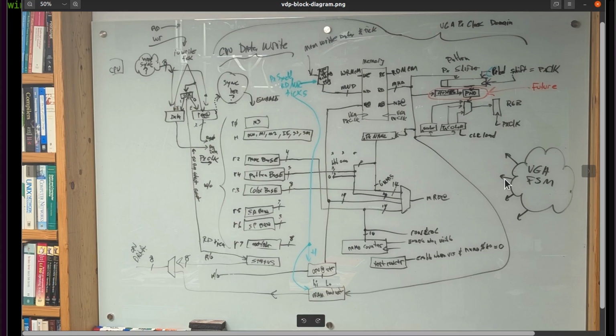So what we're going to see in the memory in my VRAM implementation is kind of a priority access read that the FSM, the state machine here, can assert whenever it wants. It'll take precedence over if the CPU wants to read, okay? And I'm going to do it in such a way that neither of these ever has to block, okay? Short of it is that as long as the finite state machine doesn't hog access to the memory, we can kind of time share and interleave access to this, okay? The details we'll see in another video.